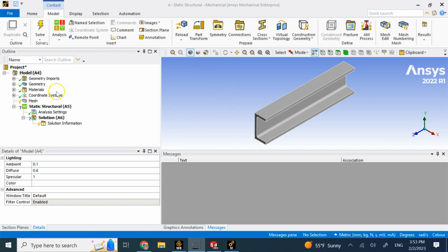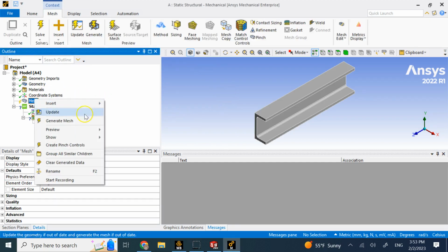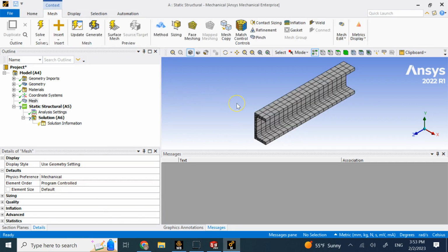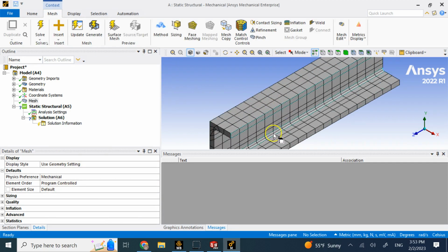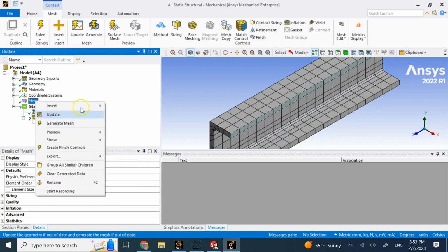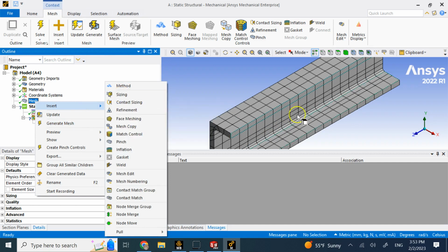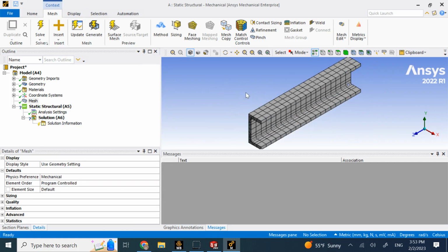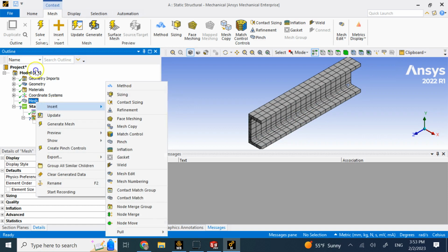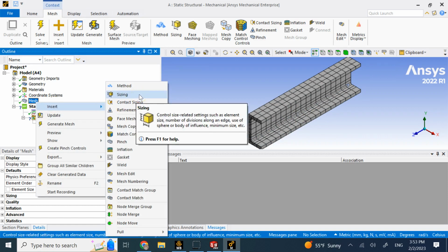Okay, so here we are in 3D. We can first generate a mesh. And if the mesh is not appropriate, we can always change it. So here it is relatively good, except maybe these areas you need to resize. So I can go ahead and create sizing now for 3D. I'll discuss meshing in one of my future videos, but in general, hex elements, which are basically like a prism, are way better and faster compared to tetrahedral elements. So these are good if they are possible.